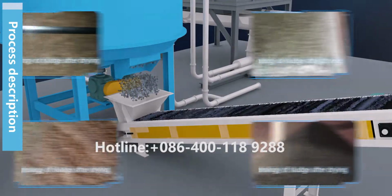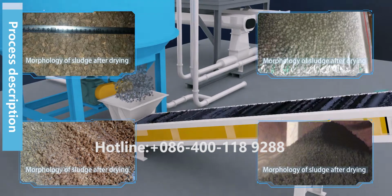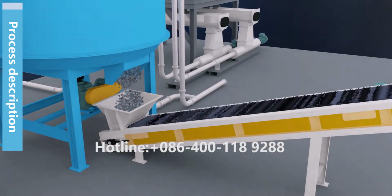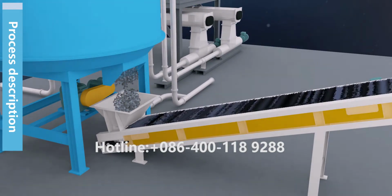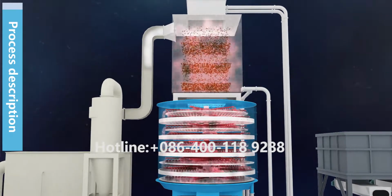After granulation and drying, the particles are uniform in size, with a 5 to 10 millimeter diameter. A roller can be installed at the bottom of the disc dryer to get sludge powder for other applications. The dried sludge is transferred for further treatment.